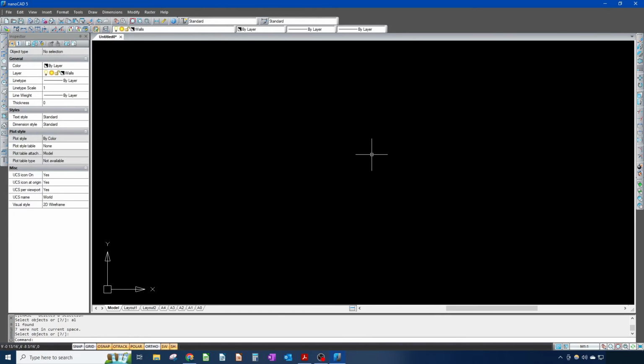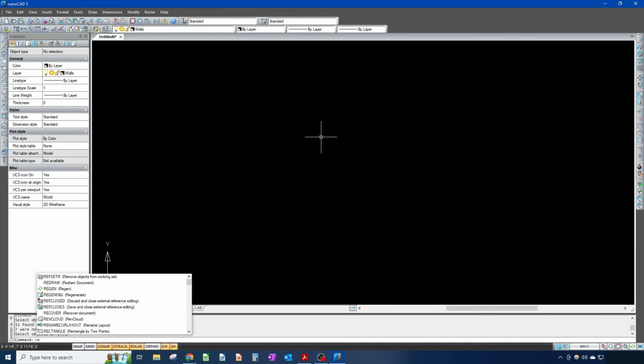Okay, so today, let's just get started with a quick little shack. Oh, also keep in mind, this is your coordinate system. Personally, I just ignore it as long as you're using the at symbol whenever you're drawing coordinates, you really don't need to reference this at all. Okay, so let's start with our basic walls.